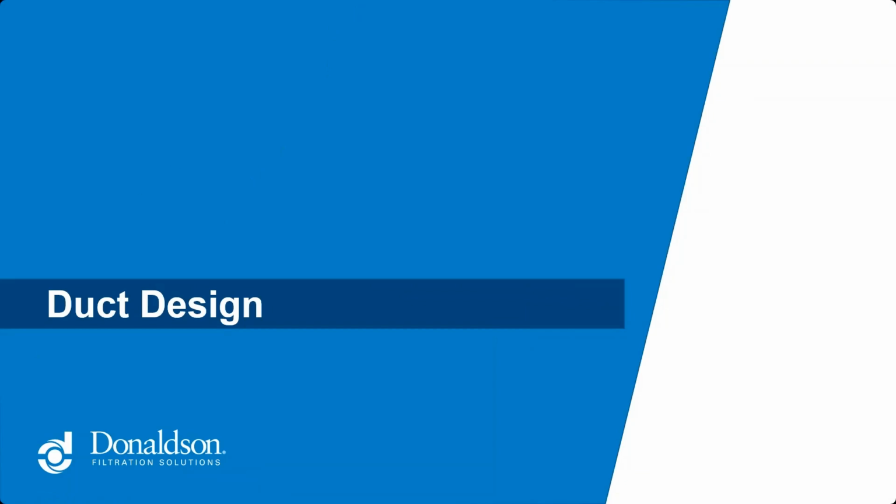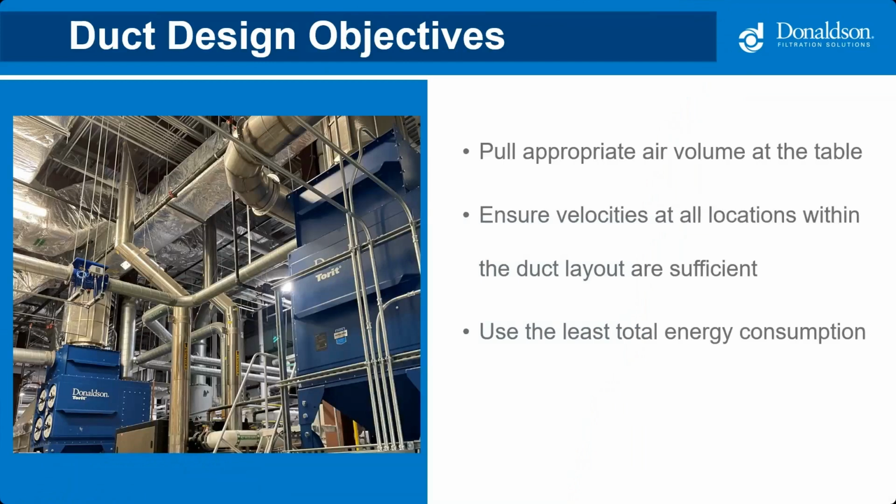Yeah, thanks, Amy. All right, so once we move the contaminant from the laser table itself, the goal is to move it into the filtration system through a series of ducts. So when we're looking at duct design, a properly designed duct system should include a few different things. It should be able to pull the minimum airflow required at the table. It should be able to maintain velocities required to transport that material through the duct without dropout to the collector, and use the least amount of energy possible while minimizing any wear and tear on the duct components.